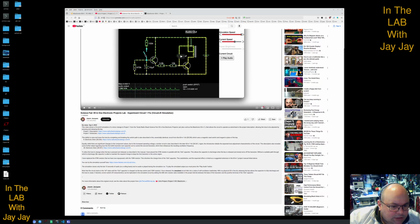To allow the tone to change when the key is pressed and released, as described in the manual, I have placed the 470k resistor in parallel with the 10 µF capacitor. This allows the capacitor to discharge when the key is released and slowly turns off the transistor. Without a suitable path through which to discharge, the capacitor is able to maintain the required charge to keep the first transistor in the active region.